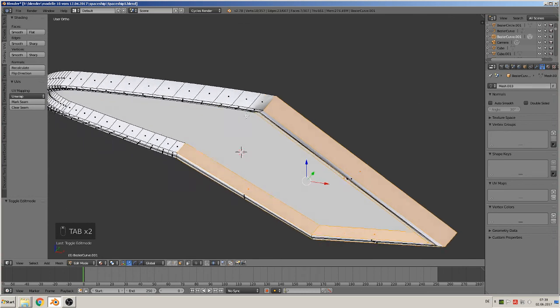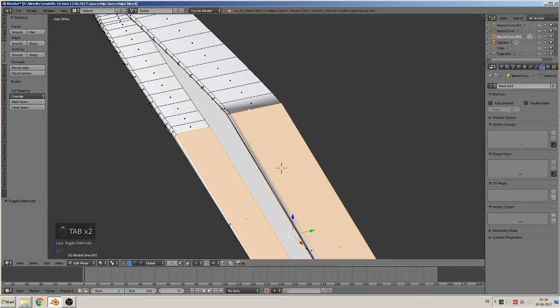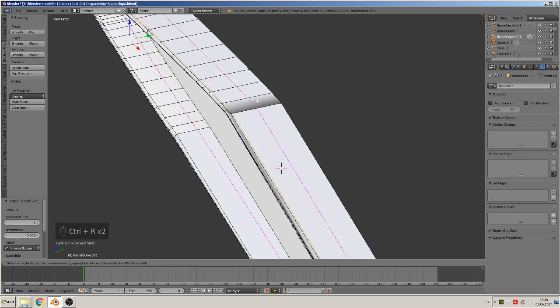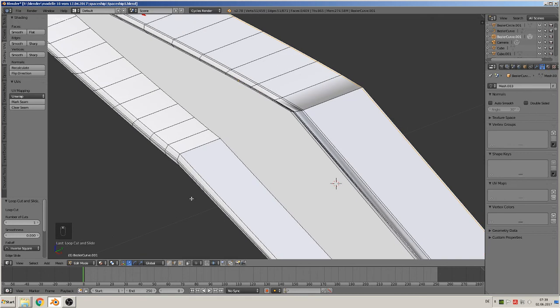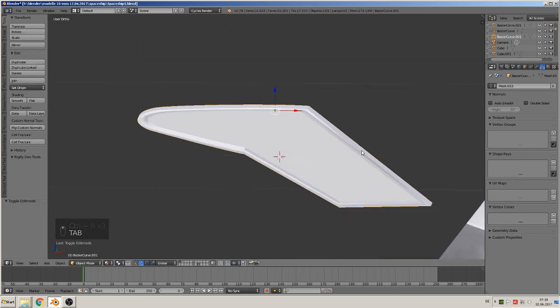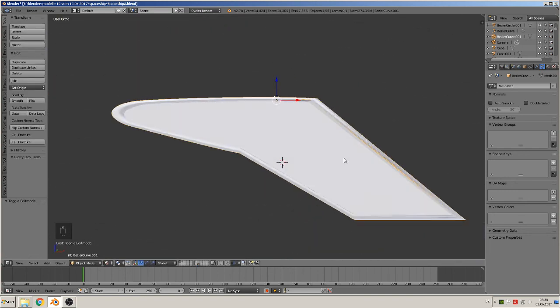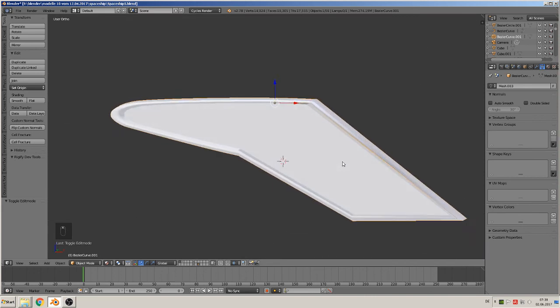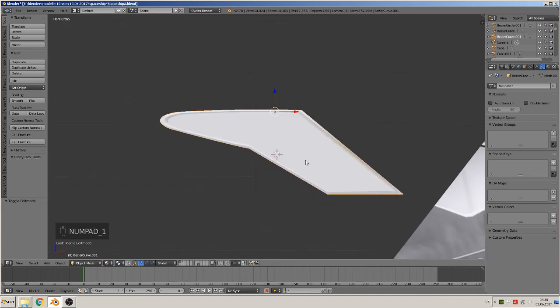Then we see the other errors come logically from the shading errors, so we put in here 2 loops. Then we can bring them out. This one here we can heal by doing 1, and this one here needs 2 others. Good. We can sharpen that later with the remesh modifier or something else. That isn't the point at the moment.